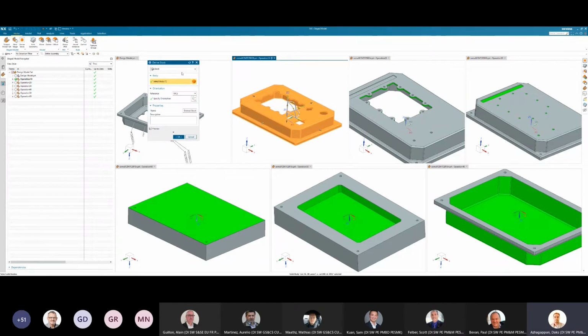we can obviously select, let me click on this one here. So if I go into the settings, I'm going to select the geometry, the engineering data, and in the settings you can provide how much you want to offset on all sides. So basically on X, Y, and Z directions. You can see here on all 3 different directions, you can key in all the clearances. Sometimes along positive X, I will give you more thickness than the left side of the X axis, right? So you can define different thickness.